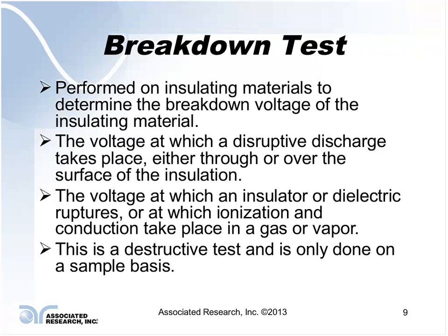A voltage is applied to the insulation and ramped up to the point where the insulation actually fails, and it will discharge either through or across the insulating material, indicating a failure. The voltage at which the insulation or dielectric ruptures or ionizes, and the condition takes place in either a gas or vapor.